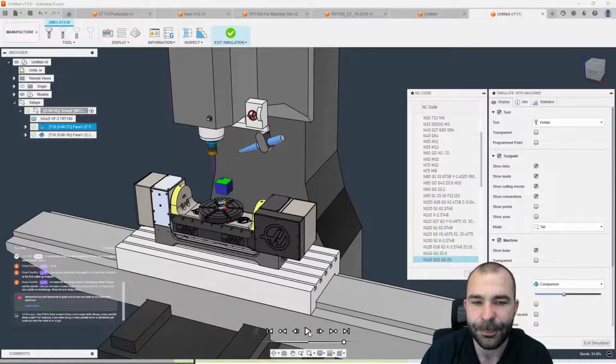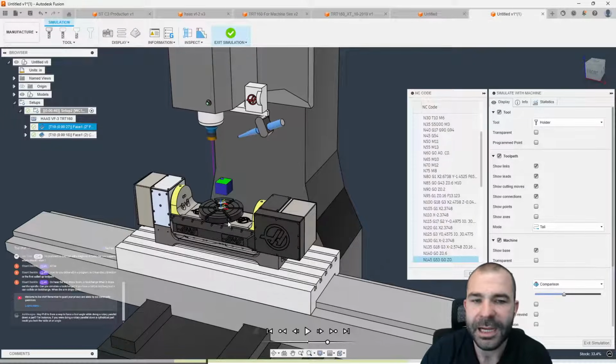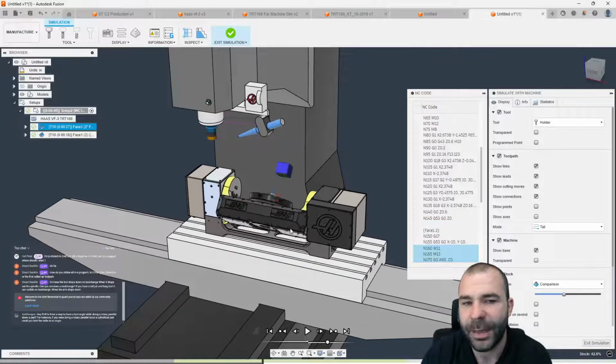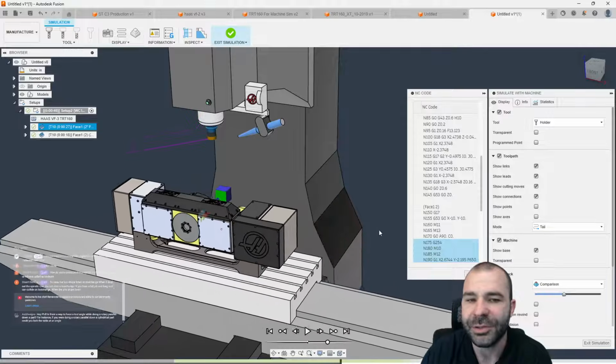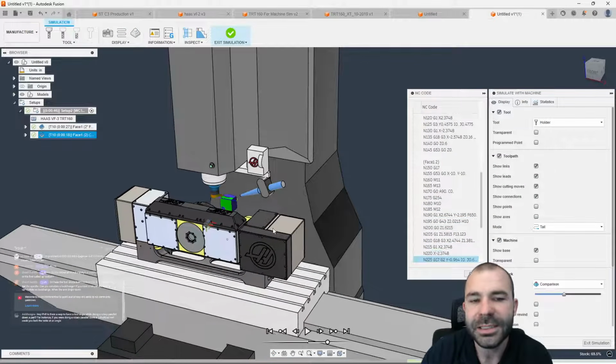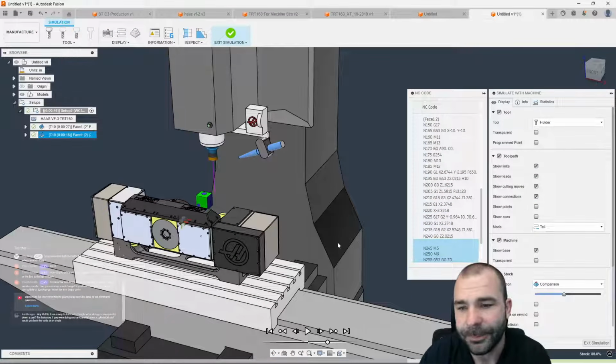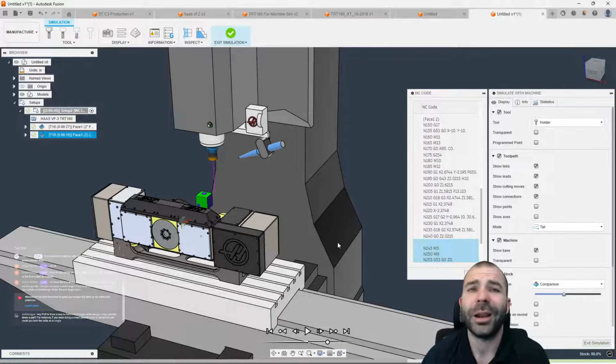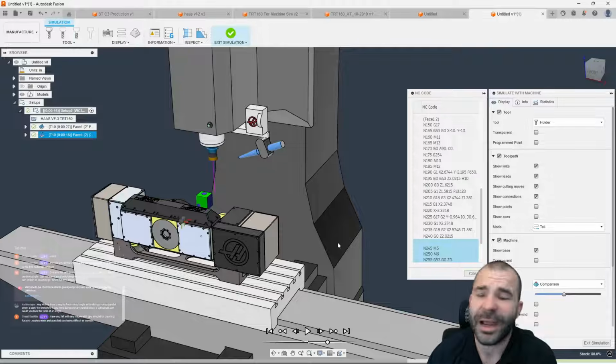So let's go ahead and hit play. As you guys can see, that was very quick. We have now jumped down. We've faced off our part. And as I click and drag on my screen, we go back to our home position. We're now tilting and coming back over to continuously machine our part. Now, again, we could handle this in the machine sim, as you guys can see. On a lot of controllers, you can actually define that at the controller.